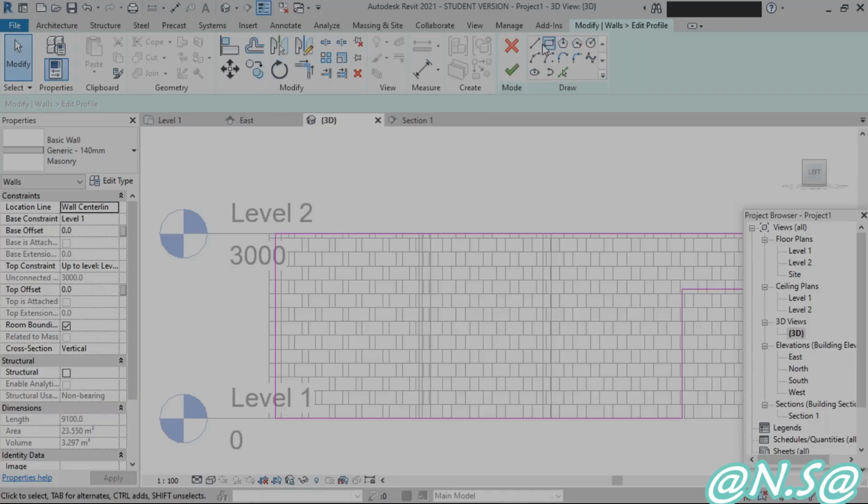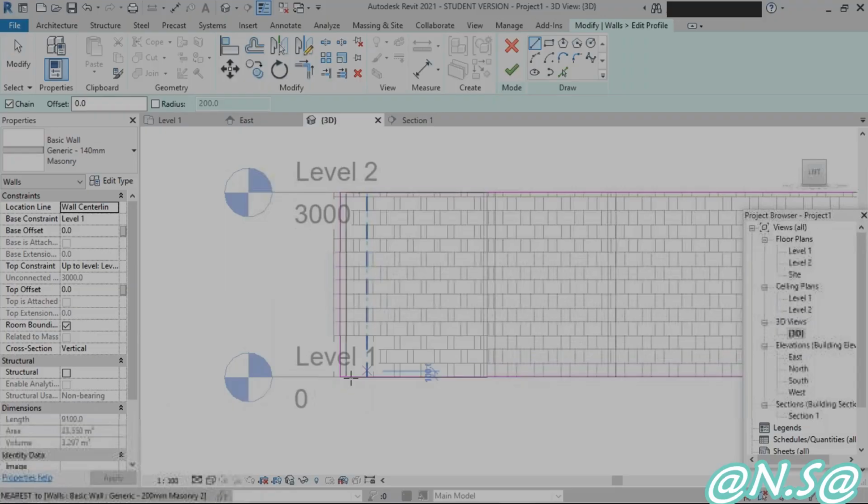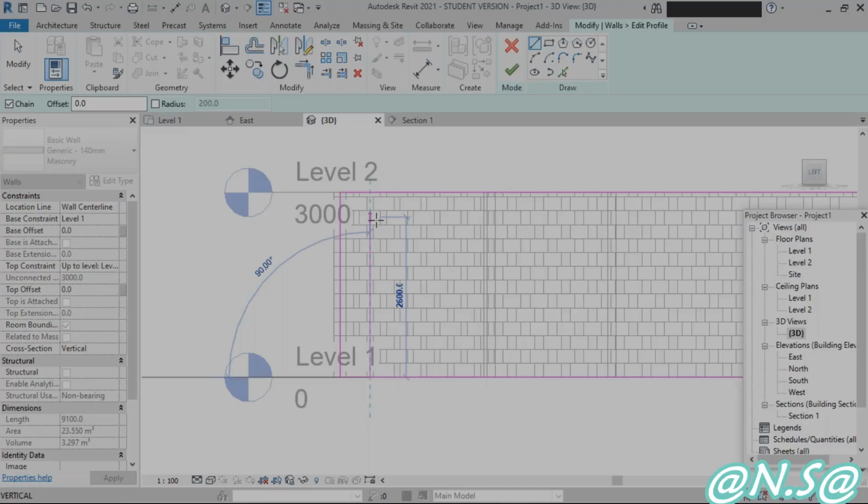By using these draw tools, first I'll use this line. From this corner I first give the reference and slightly move the cursor, so you will get the dimension axis there. So 1.5 meters, by leaving 0.5 meters I'll start drawing here, specify first point, next 2600 or 2100 I'm giving the height.